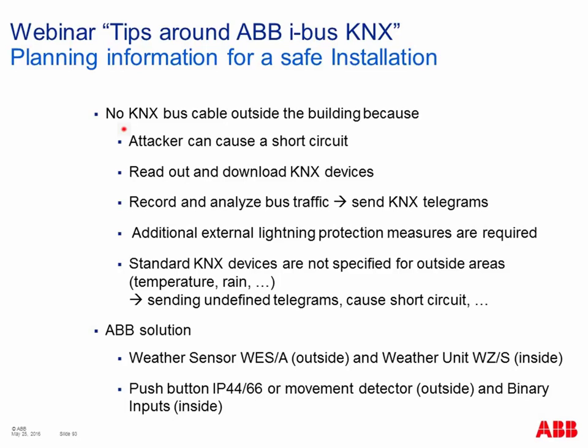And of course, he can download to KNX devices, for example a download with no group addresses, to manipulate. Or he can record the bus traffic via the group monitor and analyze the telegrams. When he knows, okay, this is a telegram for some special feature, for a special scene, a goodbye scene or a welcome scene, then he can also manipulate and send the telegram.